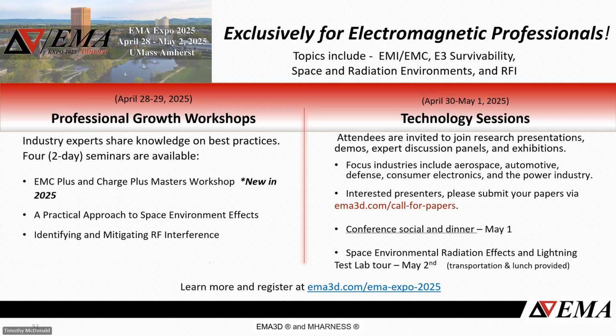Okay, next question, and this is a pretty interesting one. I am aware of the capability of exporting the near field from SI-Wave or HFSS to EMC Plus in order to perform PCB radiation scenarios. What if my intention was to do such an analysis completely within the EMC Plus tool? The question would be, is it possible to assign active component models like SPICE or IBIS to the EMC Plus ports and run a time domain simulation?